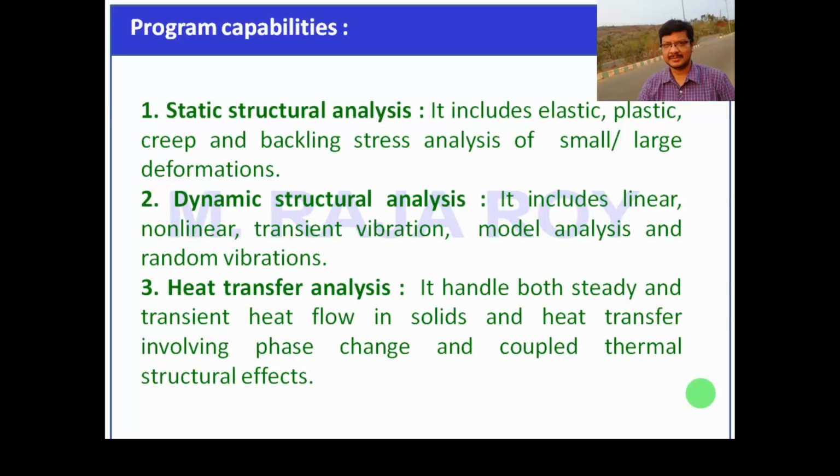Program capabilities. Static structural analysis includes elastic, plastic, creep and buckling stress analysis of small and large deformations. Dynamic structural analysis includes linear, nonlinear, transient vibration, modal analysis and random vibrations. Heat transfer analysis handles both steady and transient heat flow in solids and heat transfer involving phase change and coupled thermal structural effects.